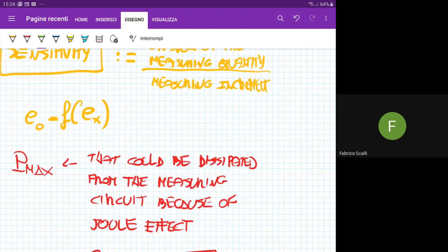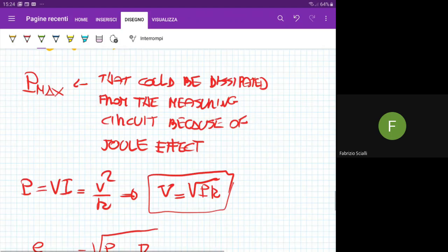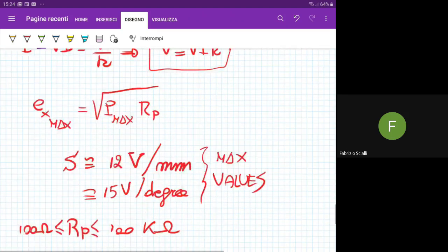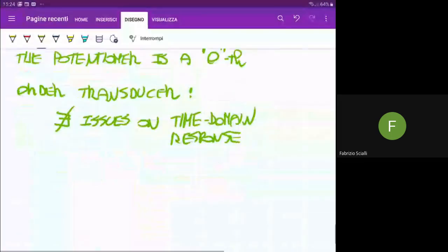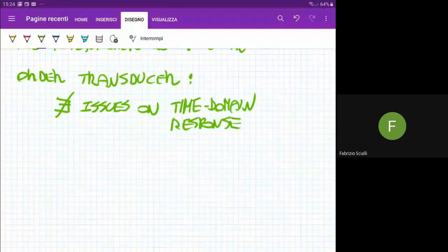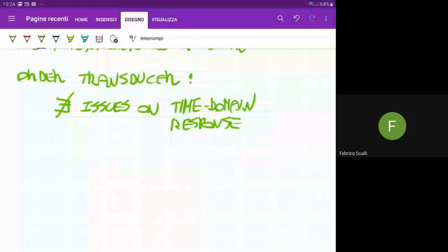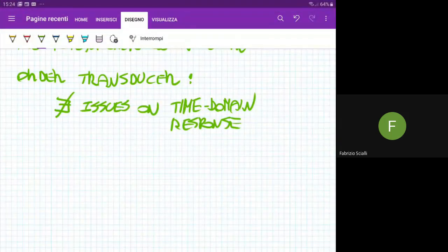And the other point, on the contrary, that I'm telling you right now, is that those potentiometers are very sensitive to the operating condition, to the environment itself. That's because of the contact. You need to have a mechanical contact between the internal resistance and the actual displacement.